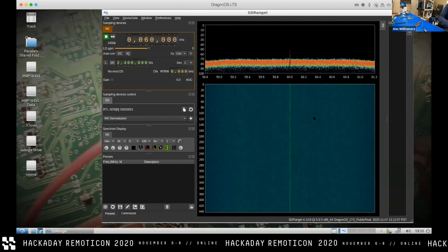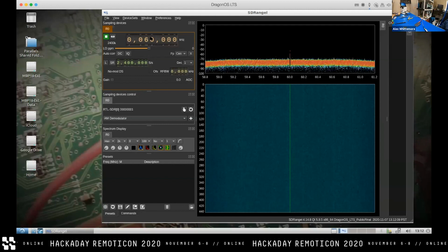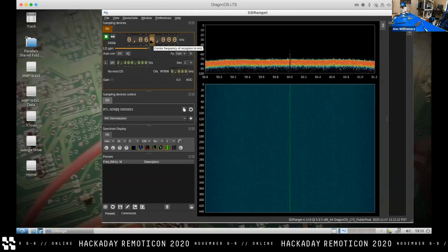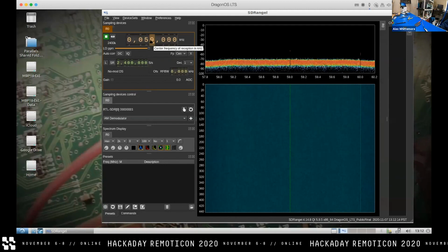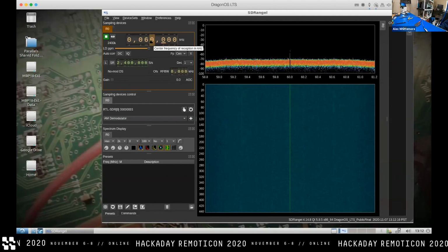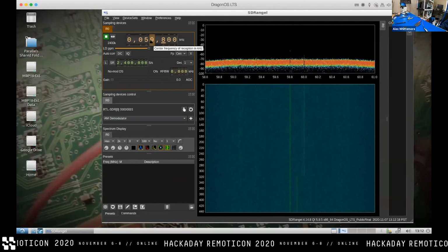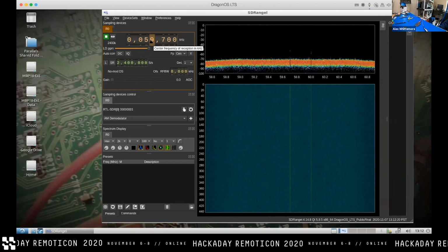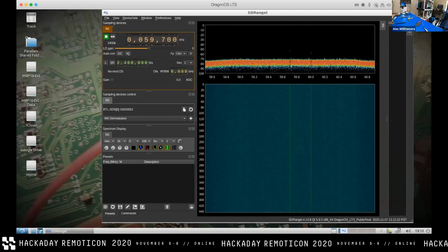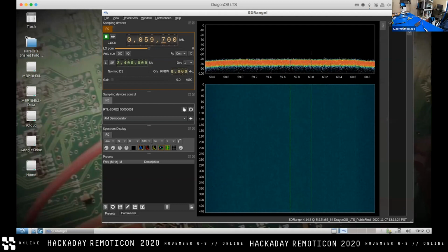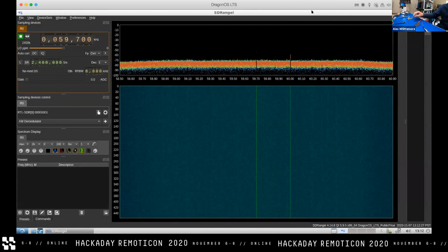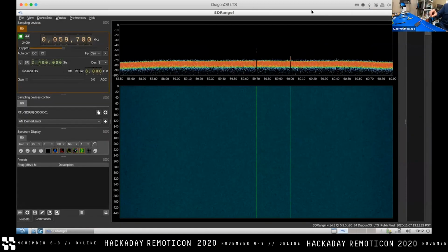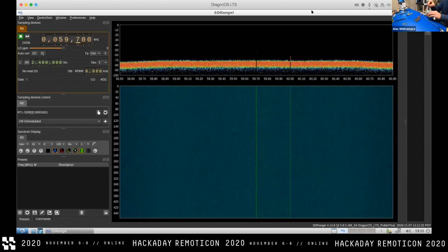Because we have that problem at the exact tuning frequency and we know that this signal is at 60 megahertz, I'm going to drop off slightly so that now, actually I'll drop off more slightly. So now we're actually interested in this peak over here. This way we're not conflating the signal that we're actually interested in measuring with whatever bias point we found.